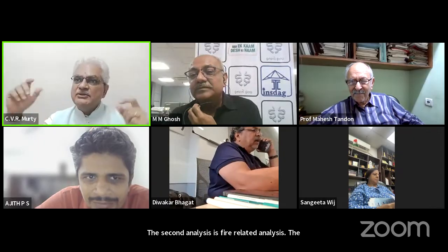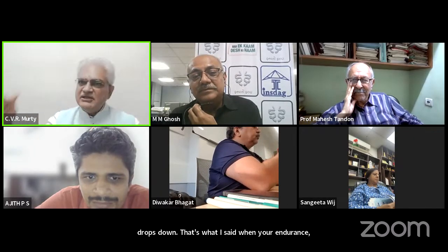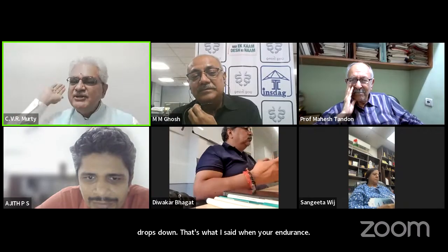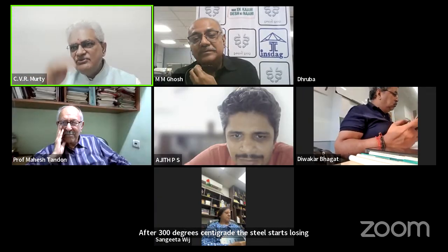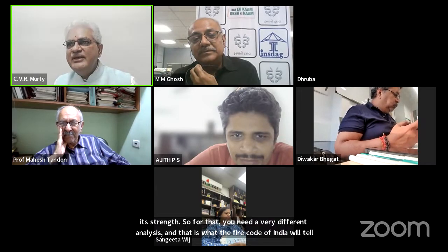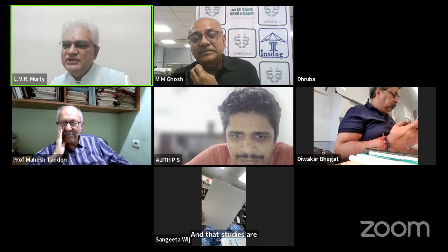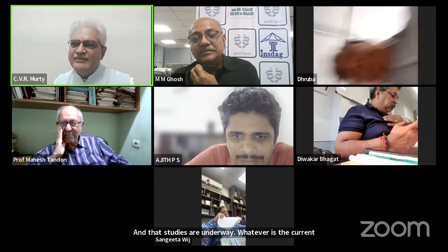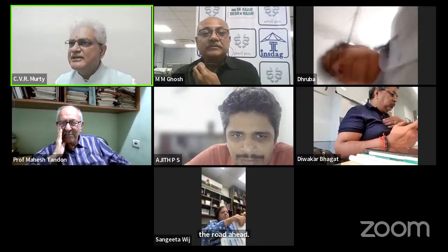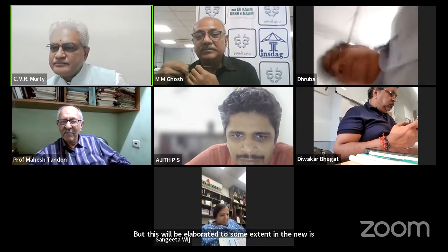That's what I said. After 300 degrees centigrade, the steel starts losing its strength. So for that, you need a very different analysis, and that is what the Fire Code of India will tell us. And those studies are underway. Whatever is the current fire code, a significant revision should happen soon in the road ahead. But this will be elaborated to some extent in the new NBC that is coming, and you will hear it in that.